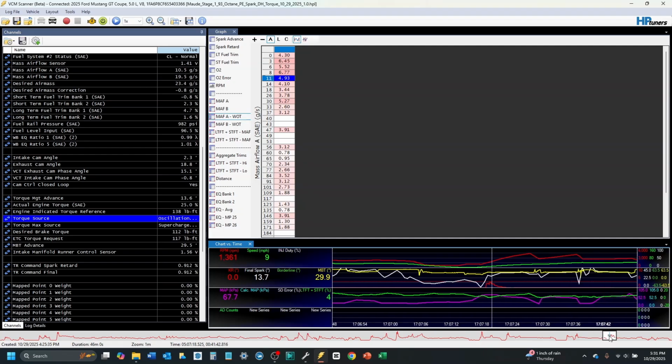And we're going to talk more about this when we get to the actual torque method. And I'm going to look up more about oscillation. And I wonder if that is the same as something else I was looking at. Yep, the anti-shuffle. Okay. So anti-shuffle helps balance things if you've got a wiggly foot on the pedal. It just helps smooth out low-end acceleration. It's not a bad thing. And you see here for the most part where I'm really hitting it though, again, all driver demand. Oscillation, because we're bouncing around a little, driver demand. It's exactly what I want to see.